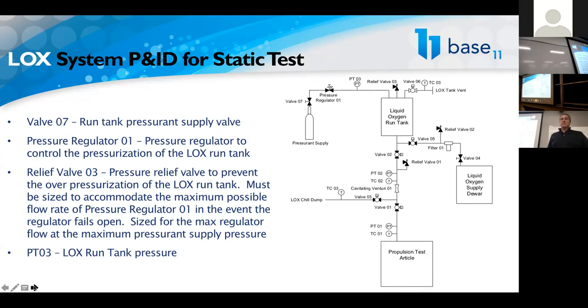And so that over time can lead to significant, intimately bound up contamination that could be a massive hazard. So the cleanliness aspect with nitrous oxide is every bit as great as it is with LOX, if not even more.